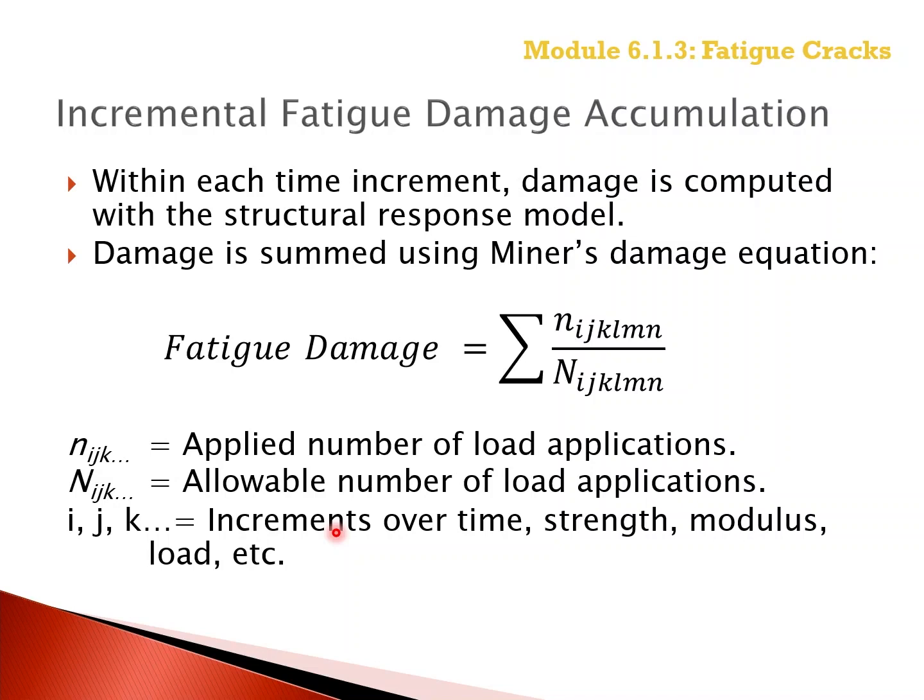Many of the other pavement inputs also vary throughout the year and have an impact on the calculated tensile strain. For example, the stiffness of the underlying subgrade and the stiffness and thickness of any underlying aggregate base and or subgrade layers and whether they're stabilized all have an impact on the calculated tensile strain.